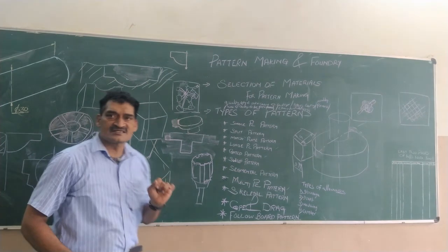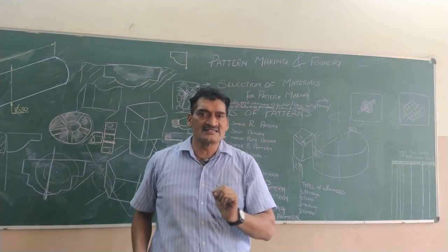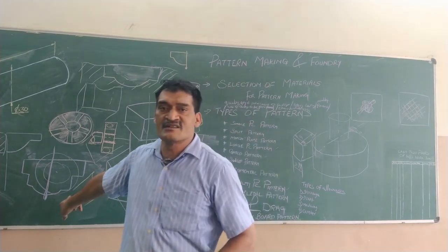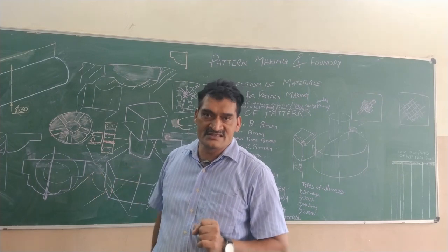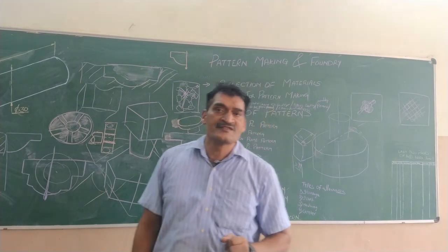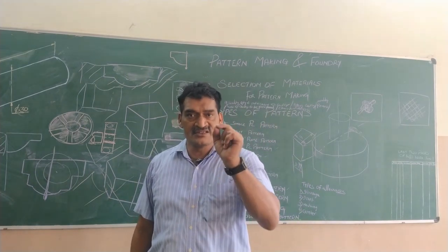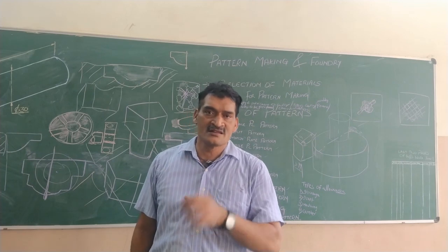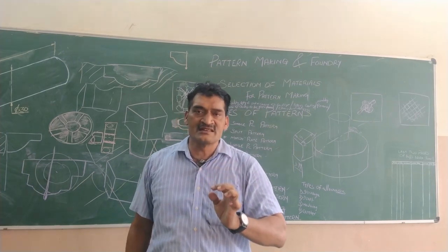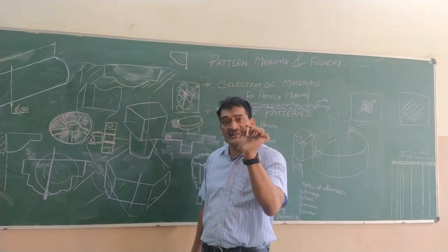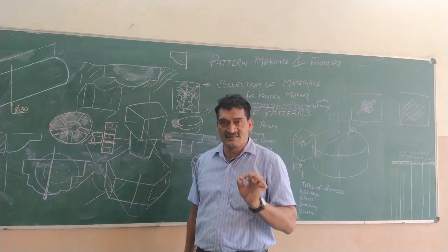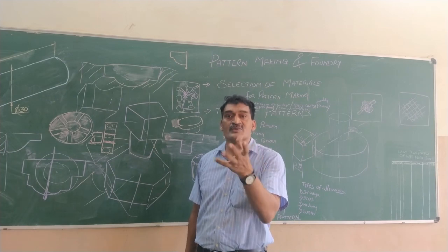As it moves, it requires a little clearance. Let's say the diameter of this is 2 inches or 50.05 millimeters, whereas the so-called bore is 50.00. So what happens? The bore diameter is small, so you cannot force the piston in. So you require a little clearance. Your bore should be 50.1. There should be some clearance, not too much.